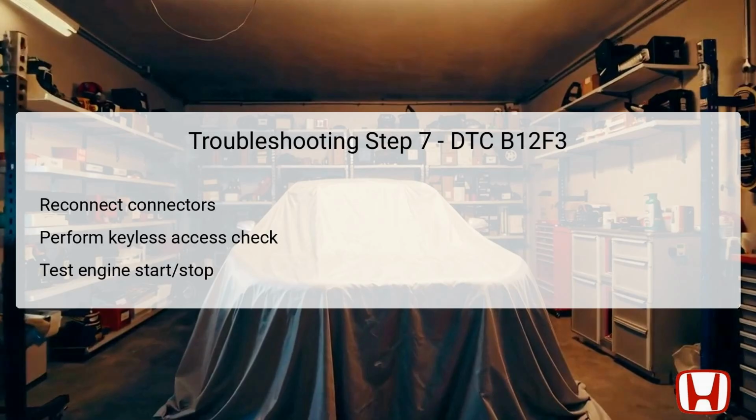If successful, it means the system works as expected, and the communication issue may have been resolved, allowing the process to continue to the final step. However, if the mode does not change, replacing the body control module may be necessary.